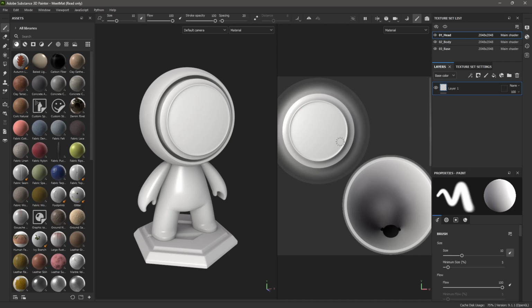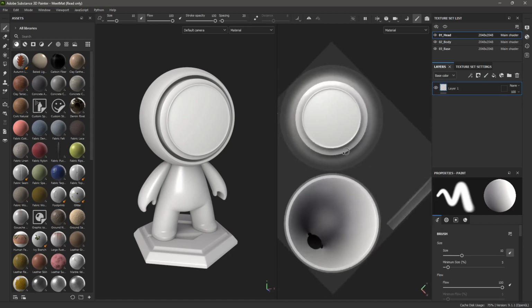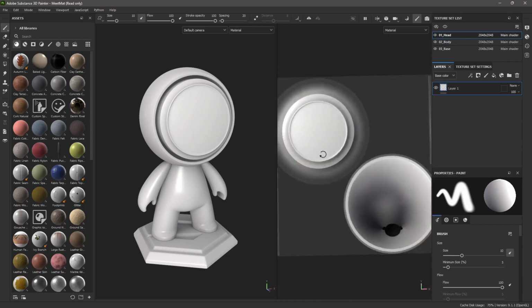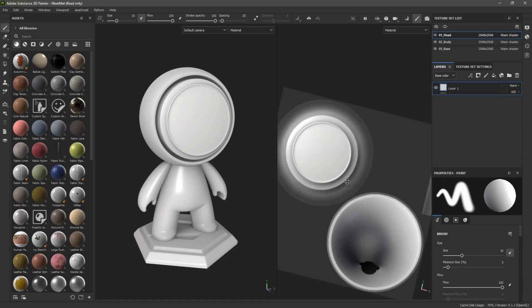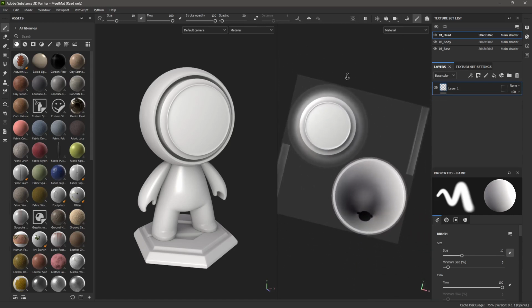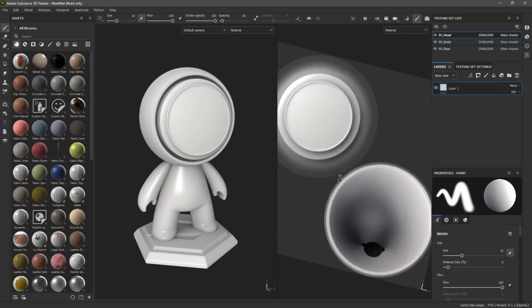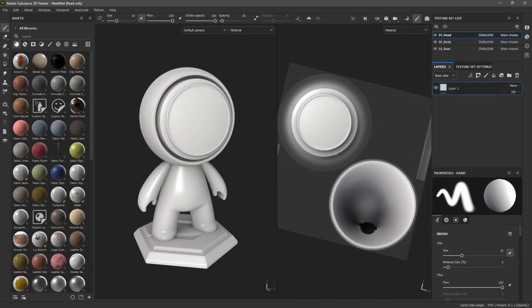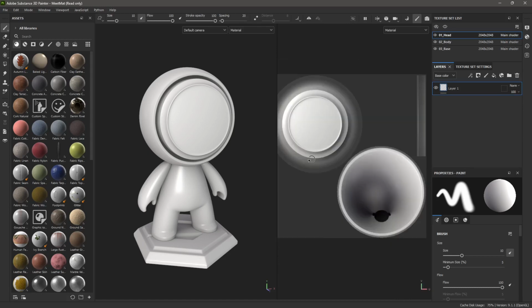So you can press the Alt, and if you click with the left mouse, it's going to rotate. If you click with the middle mouse, it's going to pan. And if you click with the right mouse, it's going to zoom in and out. So you can use them again in 3D or 2D. Now, if you hold also the Shift key together with the Alt key, you can also rotate, being more precise, and also do other things.